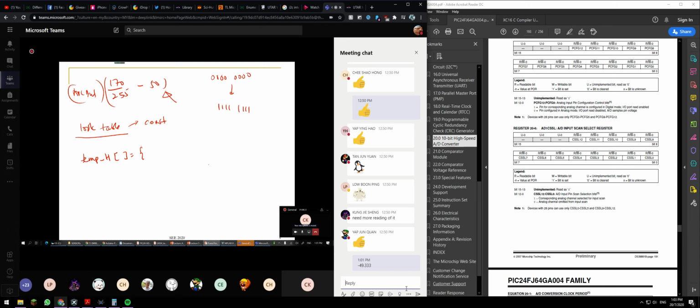Let's assume that we are using 7 segment. I simply draw my microcontroller, and I connect four 7 segment displays, or it can be LCD. So how should I do it? Those days you learn in microprocessor, I need transistors to switch it on and off. I need 4 NPN transistors and resistors.